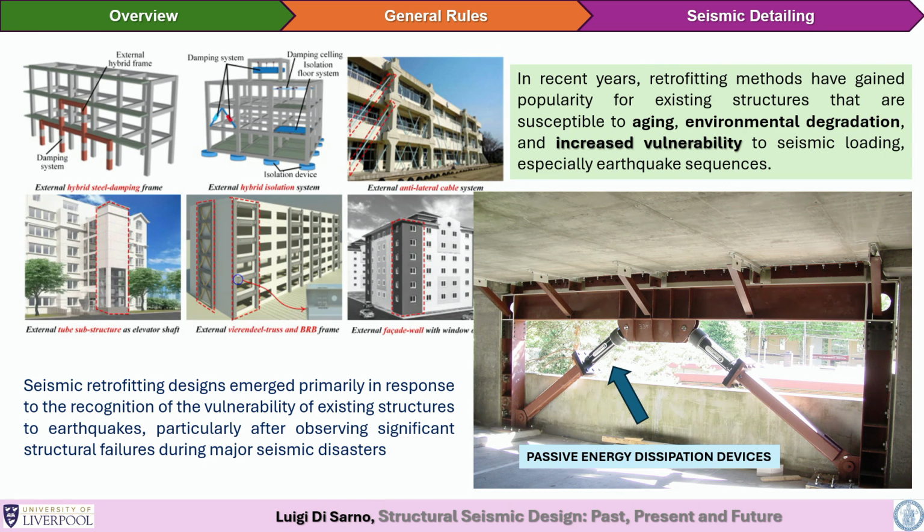The structures are also going to lose their strength. They are going to lose their stiffness. Why? Because the cover is going to spall. Then there is, for example, heavy load fatigue. There are a number of aging effects that are eroding, as with a human being. Sometimes as you age you are not always young or fit, so unfortunately you have to do some checks. I'm not going to say hospital necessarily, but at least you do checks. And checks mean that you have to go on buildings and do a new assessment, and the assessment is going to take into account all the previous history. So it means that the concrete that you initially selected as C20/25 is now becoming C18/22. How do you do that?